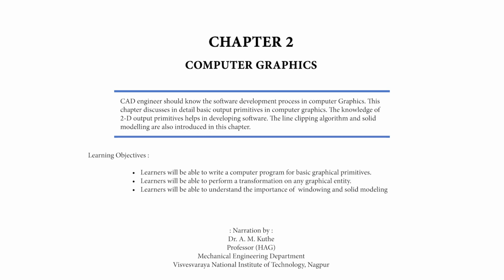Advantages. Number 1, simple to construct because of the simplicity of geometric concepts. Number 2, requires less computer time and memory. Number 3, does not require extensive training for the user. Number 4, forms the basis for surface model and solid model. Number 5, easy to clip and manipulate through the use of geometric and coordinate transformation. Number 6, it can be used in manual finite element modeling and tolerance analysis.